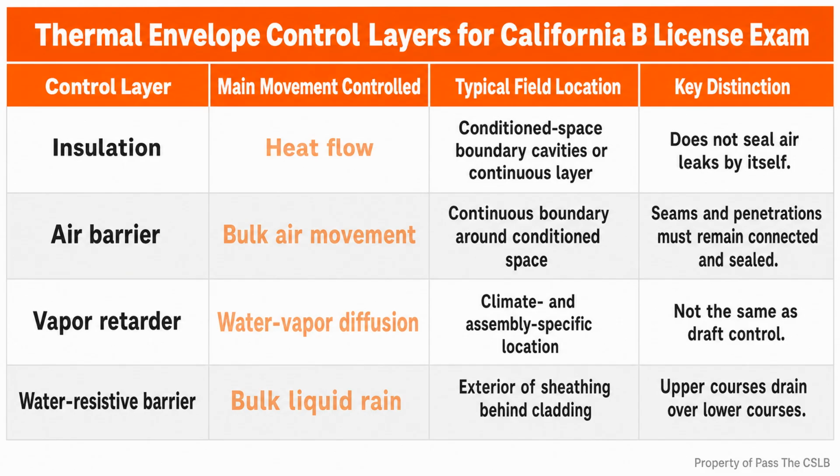The missing step may be inexpensive before placement and costly after placement. Imagine a contractor who sees the tub delivery arrive early and lets the plumbing crew set it against open exterior studs. The insulation crew later reaches every visible cavity, and the wall looks nearly complete. The hidden bay behind the tub still lacks its interior air barrier.